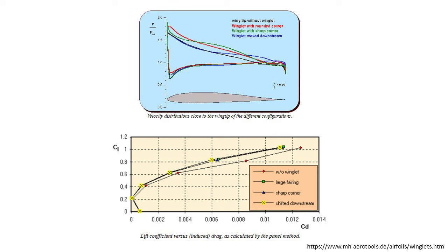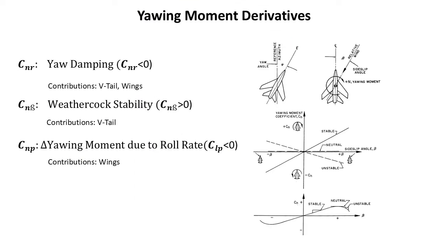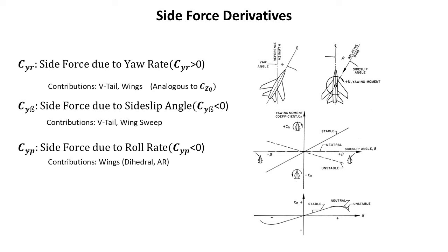Remember again that we love tailless aircraft here, at least in this series, so while the intent behind winglets is traditionally to reduce induced drag and the downwash delta due to the spanwise flows, we can use winglets as a different tool for planes with no tails and can use them to drastically increase our directional stability while still realizing some of the induced drag reduction benefits.